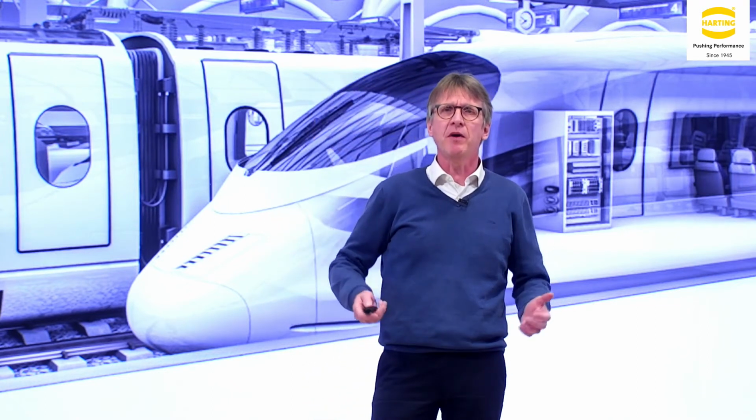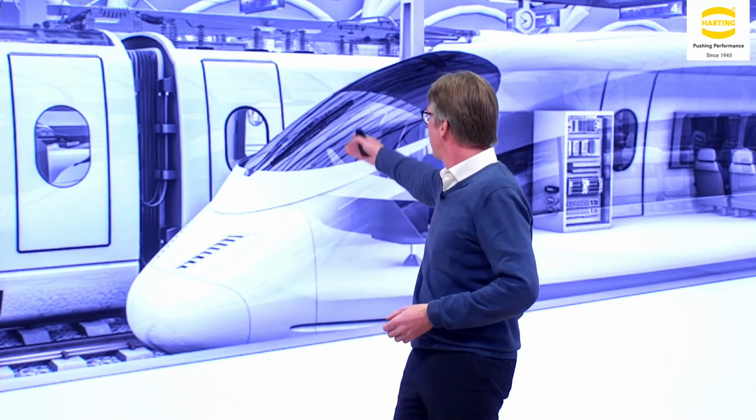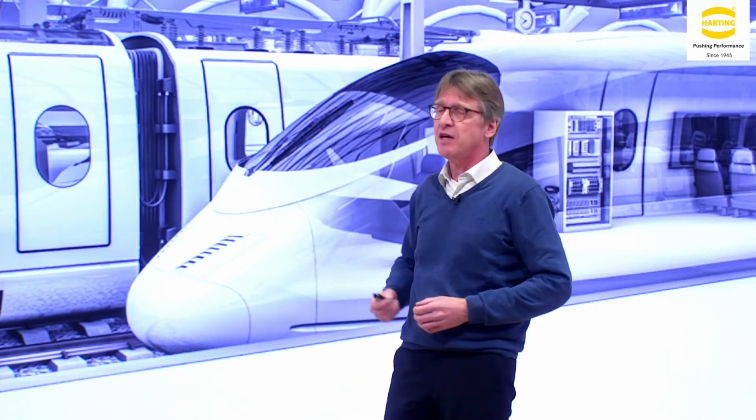Category 5 needs only 4 wires; category 6, 7, and 8 need 8 wires. With these protective conduit solutions, the corresponding cables can simply be replaced without the need for costly and time-consuming replacement of the entire system. As you can see, you can leave everything in between, just pull out the old cable and pull in the new one.